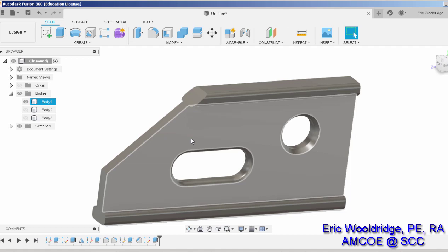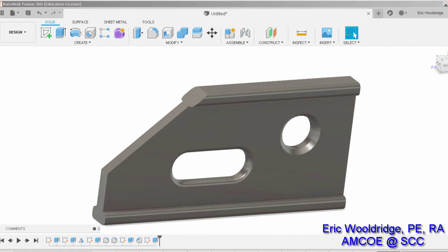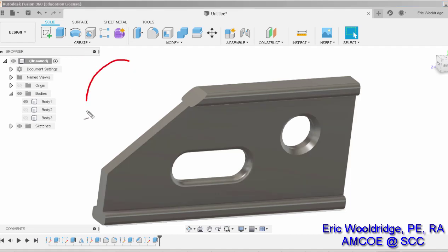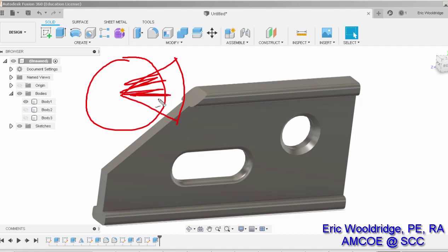Alright, so what we've learned with this process is that you can actually use objects to cut other objects when you can't get a tool to work for you. And it's not uncommon for us to do approaches this way, to make a completely rectangular or circular based feature and then go back and actually cut things out. So for example, you can think of it like cutting a pie. We could design a pie or circle real fast and then design in something to be a chopping component to actually edit out or delete out what we don't need of the object. Very common way for us to create more complex shapes if we can't get them to behave the way we want to on the front end.